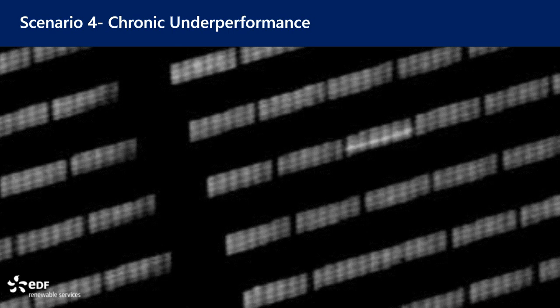Now, you would think that this would be possible to see with the tools available to your technician, right, a handheld amp clamp, doing your normal voltage and current testing. However, as I was saying earlier, this being a thin film plant, we're really looking at high voltage and low current plant designs. As a result, even at 1,000 watts per square meter, that string is showing up at less than 2 amps, right?